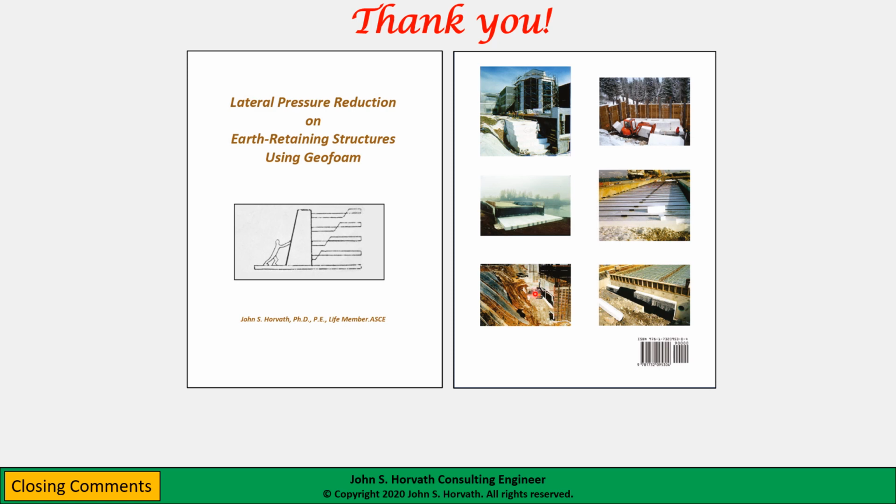This is a more distant view of a photo that I showed you close up earlier in the presentation. So in this case, the application was being used solely to reduce lateral earth pressures on the deep basement of this building from the at-rest to the active state, to reduce the cost of the exterior basement wall.